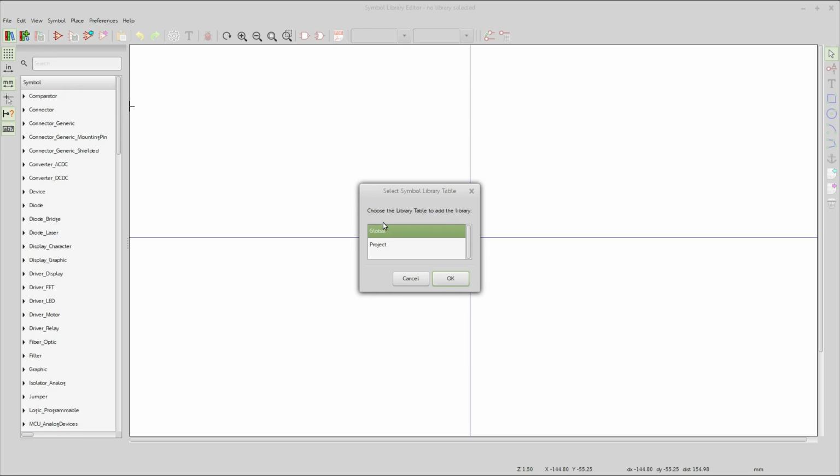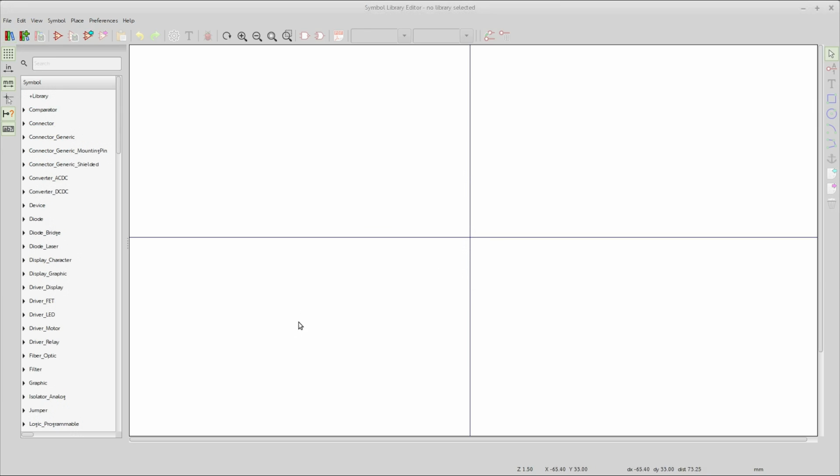Anywhere I'm at, if it's got KiCad loaded on it, I can put in the memory stick, go to my KiCad projects, start a new project, and link it to the libraries on that memory stick. And if I take it somewhere else, it's still there. So this is going to be global.